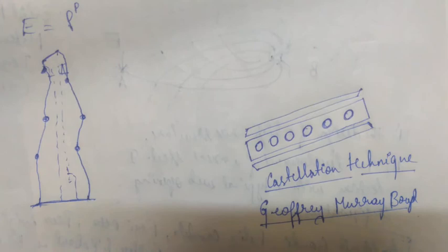The circular beams, which contain circular openings, are currently the most widely used perforated beams due to their beneficial weight to stiffness ratio and the ability to pass services, for example hydraulic pipes, electric wires, etc.